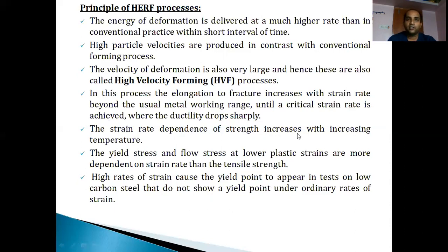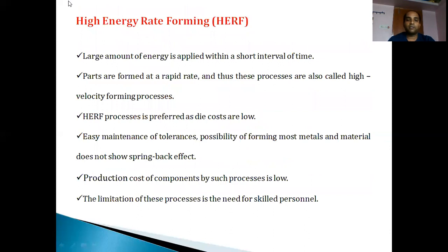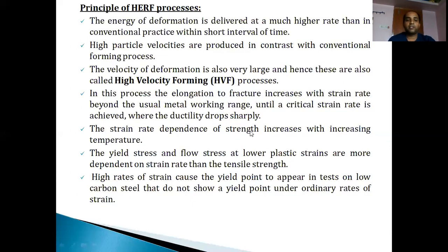That is the reason that we are learning topics known as cold forging as well as hot forging also. So when the metal is being heated within the plastic limit or beyond the plastic limit, it undergoes a strain deformation. That depends upon what? Regarding this temperature factor itself. Then already we have discussed these points regarding the yield stress and flow stress in module number 1. The same two parameters come into action during the plastic strains, and they depend upon what?